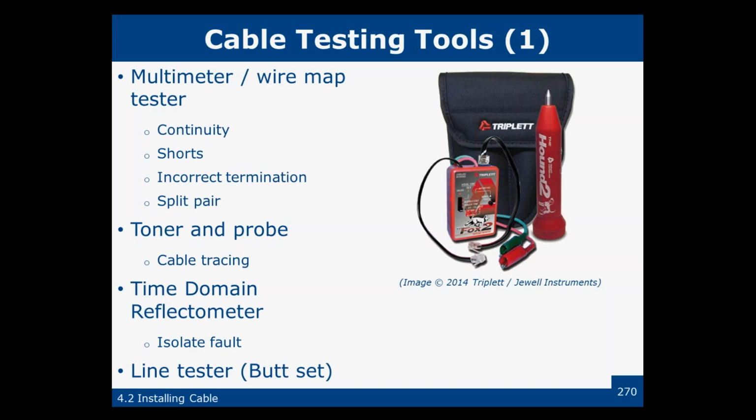The conductors in the pair have been wired to different terminals, from pin 3 to pin 6 or pin 6 to pin 3, and that's what a wire tester will tell you, whether it is actually wired correctly or not. Cross pairs: the conductors from one pair have been connected to pins belonging to a different pair. For example, pin 3 to 6 and pin 1 to 2, which is kind of like a reverse pair.